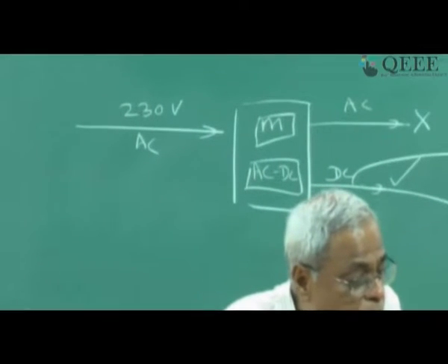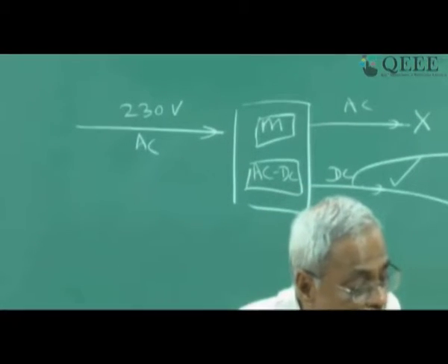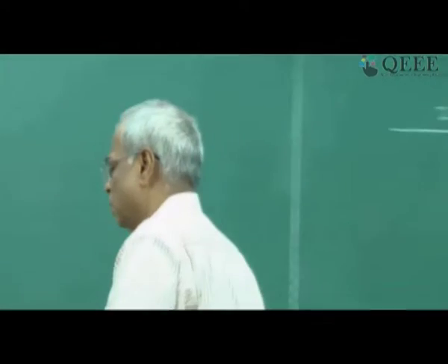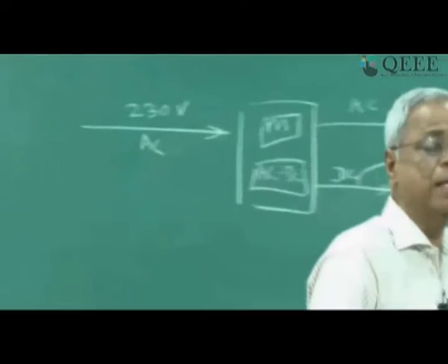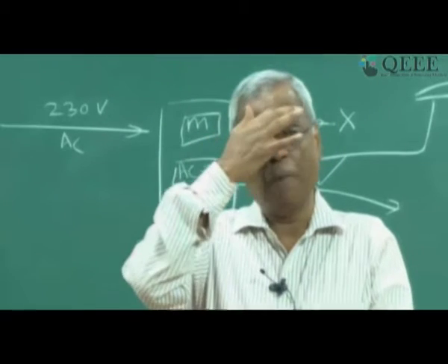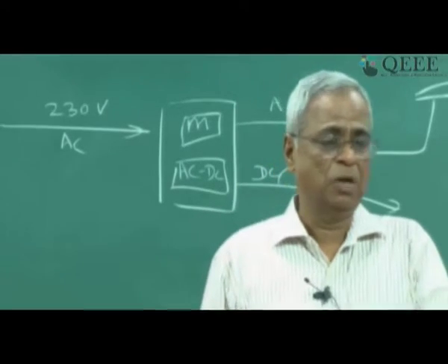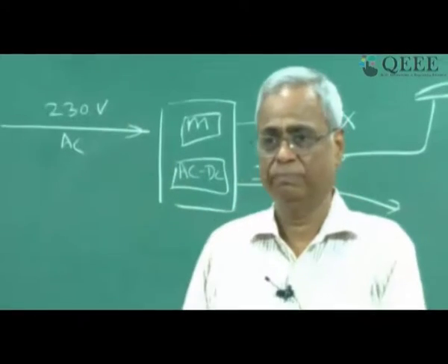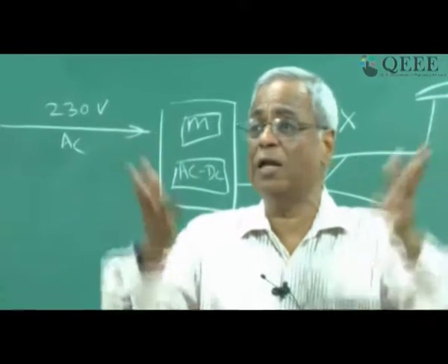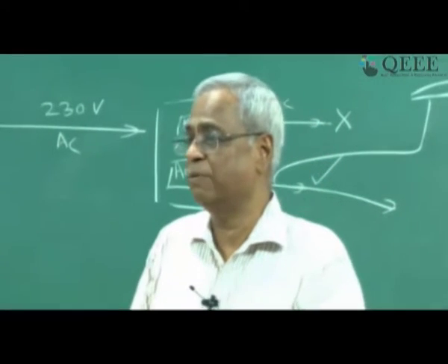Any other question? I think that question I already answered. How can 10% low power DC operate all home appliances? 10% will not operate all the home appliances. It will operate some of them. First of all, of course, DC appliances consume less power. So typically 10% will operate 2 fans, 2 lights and cell phone charging. Or you can shut off 1 fan and put in a small television. But you can add to it by adding solar. You can make it run all appliances if you are willing to put in a little money for the solar.